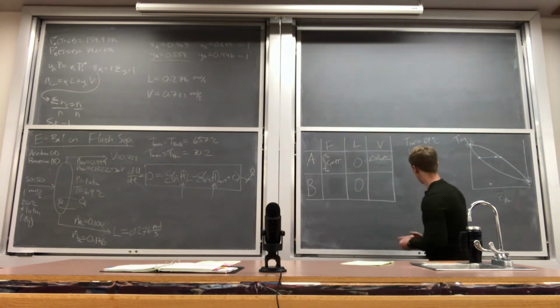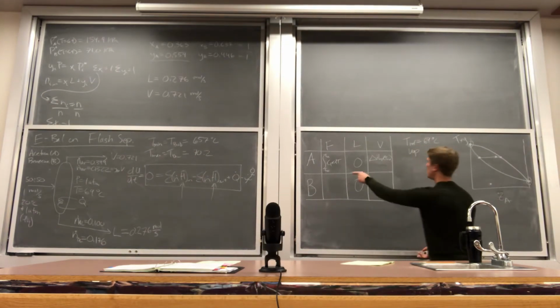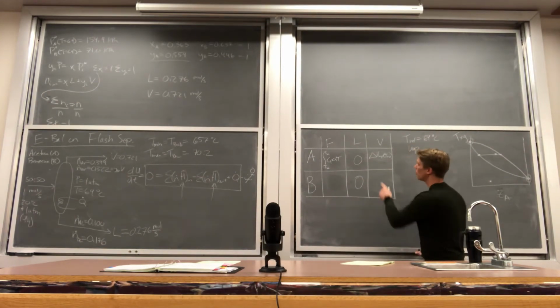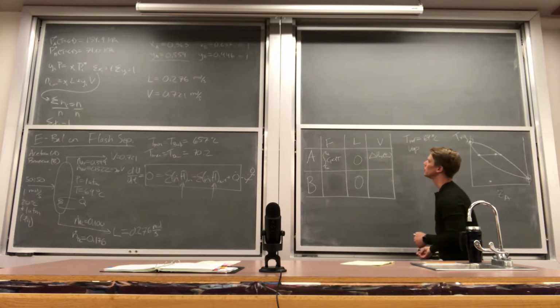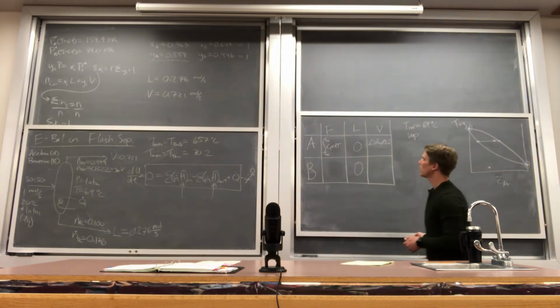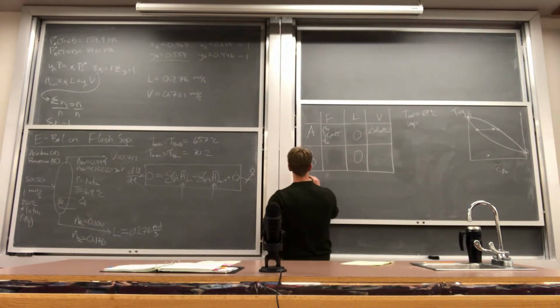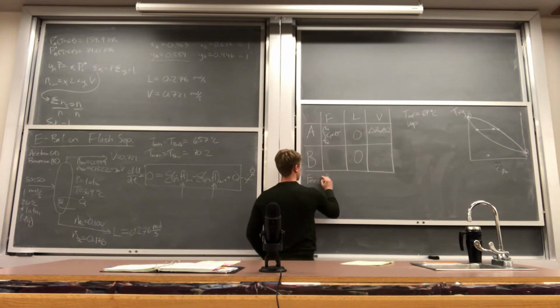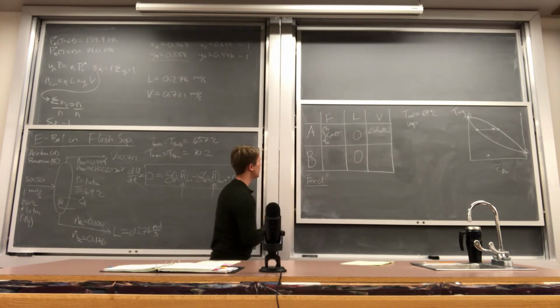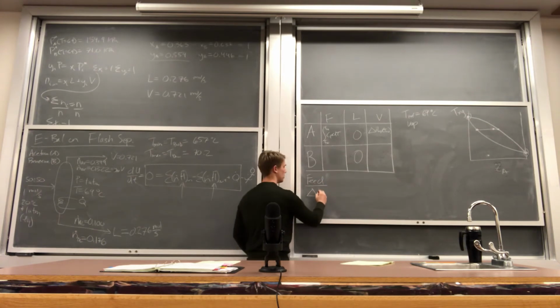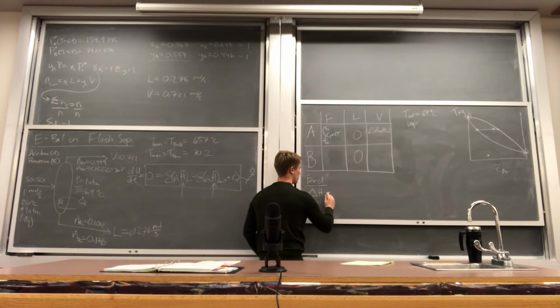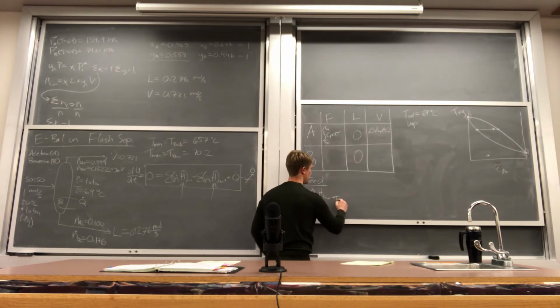So from here, the liquid one to the feed is pretty straightforward. The vapor one is where we're going to be spending a bit more of our time. We did talk about it last week, but we also had an exam, so it might have slipped away, unfortunately. So let's talk a bit about calculating the enthalpy feed. In this case here, what we're doing is calculating a delta H from T ref to T in.